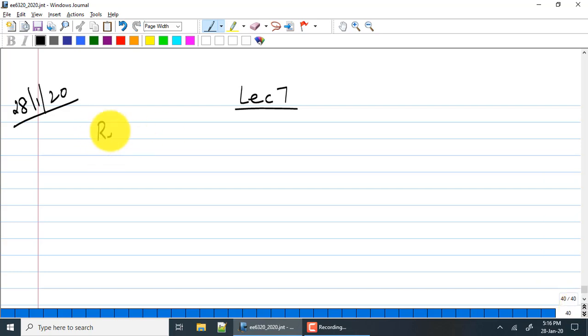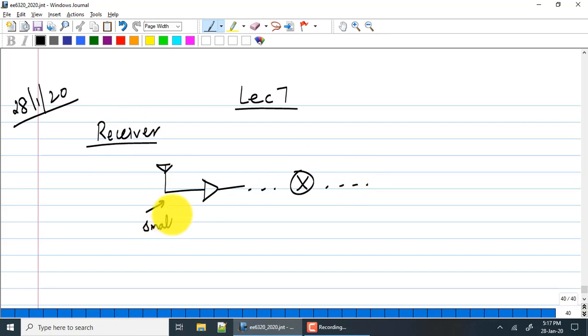So in the case of the receiver, you don't rely on the 1 dB compression point directly. Now let us look at what happens in the receiver. So maybe you have multiple guys, mixers, filters, etc. So the signal here is small, but one other thing that you see is that coming right at the input of the receiver, the antenna may have some bandwidth, but what you will very often see is a combination of signals, because this is your desired signal.